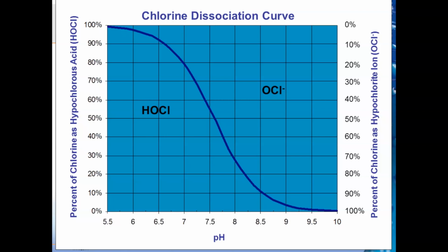Whereas as you increase that pH, that disinfection strength drops off. You can see that on the bell curve. Well, now people calculate how much sodium hypochlorite they might need to use. They do tests at the end of their process and say, well, not only don't we have any residual left over, but we have growth, or our disinfection isn't what we anticipated it being.